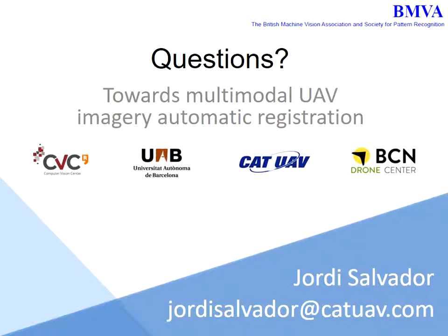Oh, you have an assumption of flat terrain. Yes, because in our case, we want to match just this single part with the bigger one. So in most cases, variations in that specific scene are not bigger. And that is why we pick the ground control points from the ground. We don't pick them from the roofs or the trees or anything that can vary because of the altitude and also the perspective.